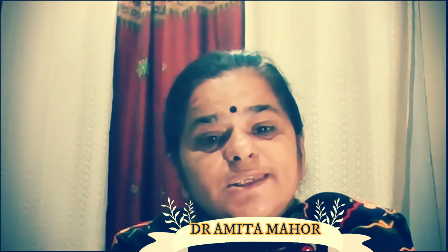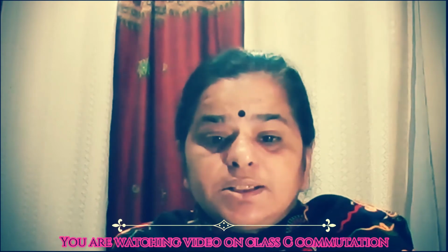Friends, my name is Amita and in this video I am going to discuss another commutation technique, that is class C commutation. I hope you are aware of commutation, but if not, commutation is the process by which an already conducting SCR can be turned off, or the process in which the SCR changes its state from forward conduction mode to forward blocking mode. There are two methods of commutation.